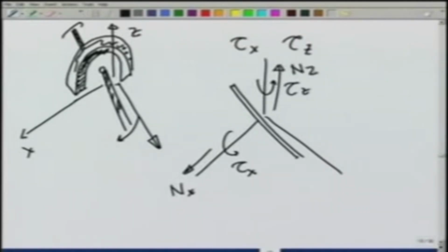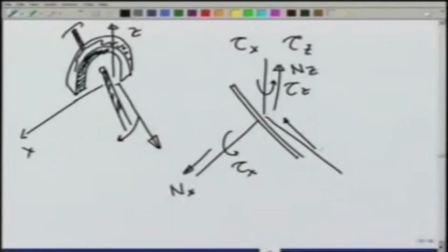So, it gives me a force in the z direction. In addition, if the shaft was completely fixed along the y axis, then it would also provide a force in y direction. If it was not free to rotate, it would also provide a torque along the y direction.